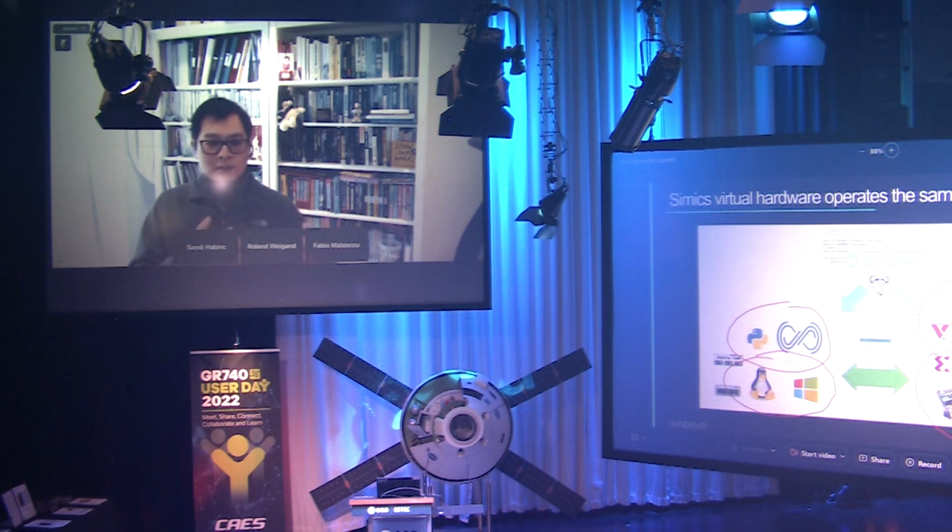So a simulator is not here to remove the need of testing on real hardware. You still need real hardware to test timing critical functionality or hardware implementation specific functionality. But what we are saying is, using a simulator and functional tests, there is a lot that can be done in a more convenient environment to do testing.